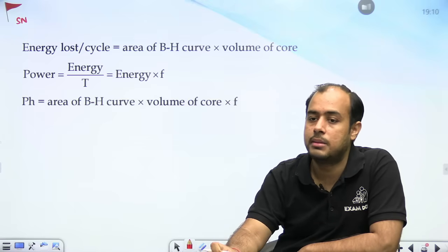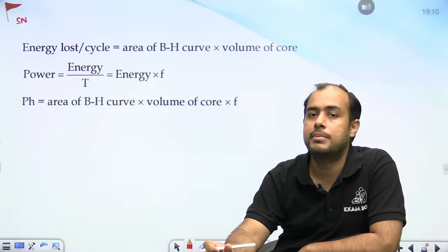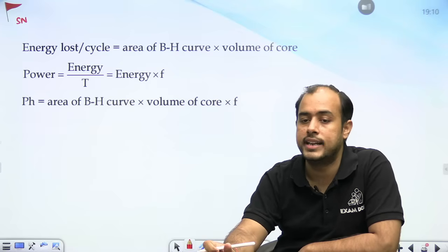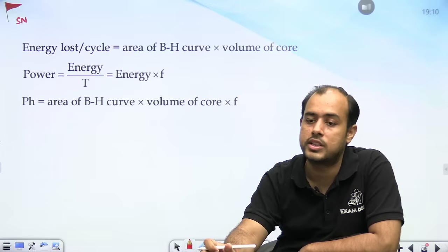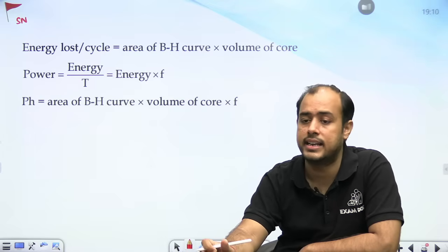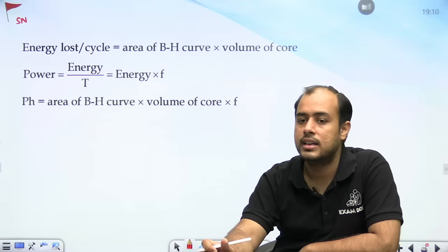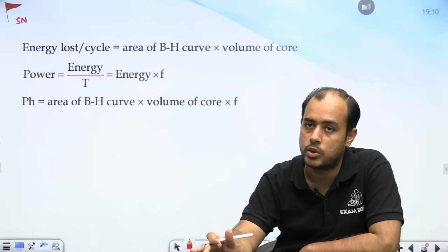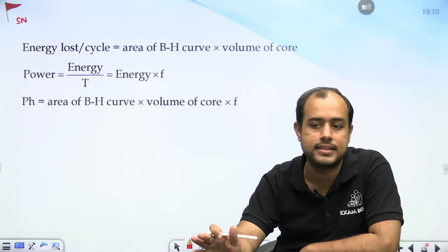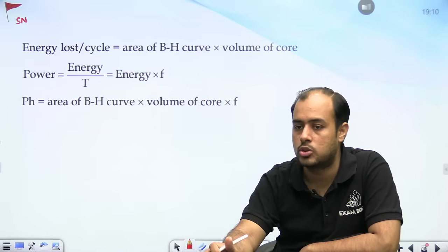तुम्हारा डाउट आई नॉट वाला, अब ये आई नॉट वाला डाउट कहां से आ गया भाई? इसका हिस्टेरेसिस से क्या मतलब? आई नॉट तो लैगिंग होता है, तो वी और आई तो एक साथ जीरो नहीं हो सकते। अरे भाई, वी और आई एक साथ जीरो क्यों नहीं होंगे? इंडक्टर का अगर करंट जीरो हो गया तो वोल्टेज तो जीरो आ ही जाएगा ना। मैं उस पॉइंट की बात कर रहा हूं कि अगर करंट आपका जीरो है, तो अगर आप करंट को परमानेंटली जीरो रखें तो वोल्टेज विल ऑल्सो स्टे जीरो। बट वैसा हम करते नहीं हैं, करंट को कभी भी परमानेंटली जीरो नहीं करते हैं। तो वैसा अगर करेंगे नहीं तो यस, वी एंड आई कैन नॉट बी जीरो टुगेदर।